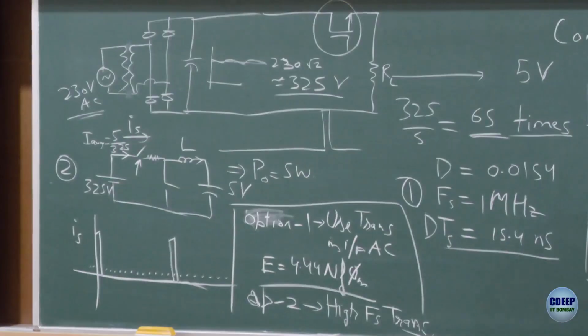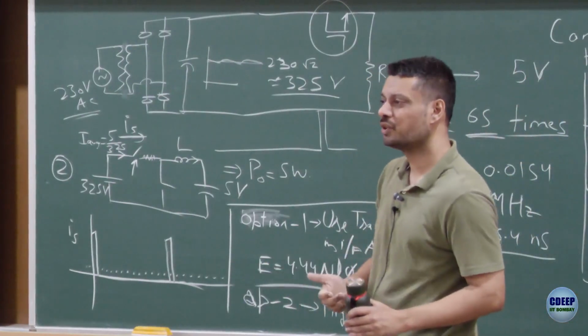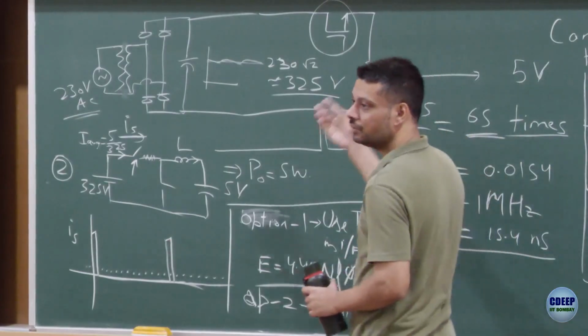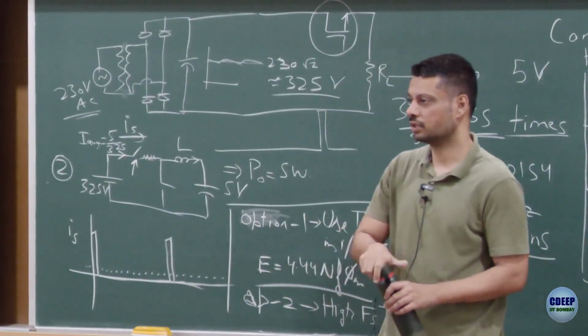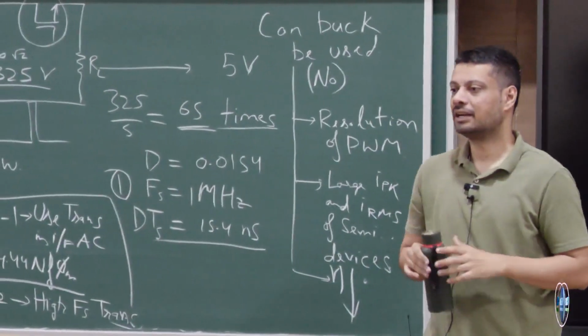Yes, the reason for the size was this low frequency transformer. The reason for heating was because we were not using a buck converter, we were using linear regulators to regulate the output voltage. By the way, has anyone seen these kinds of adapters at home?